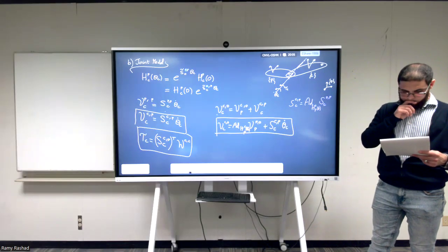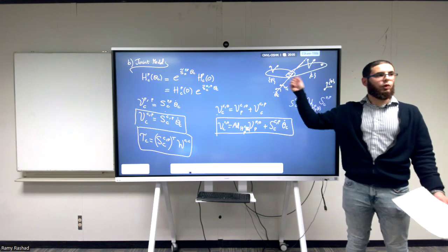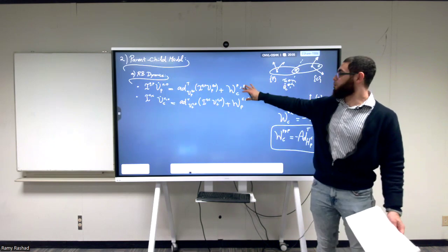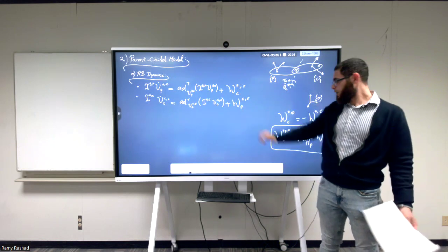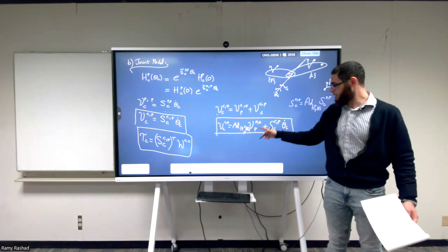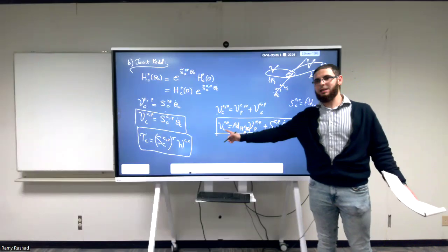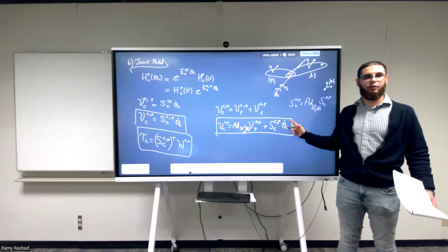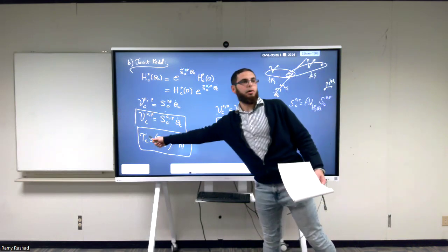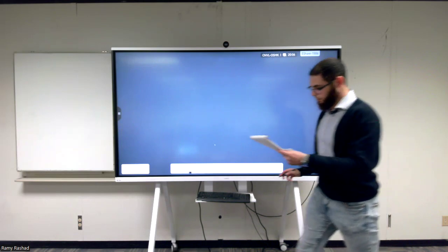Now we're going to be doing something very, very interesting. You see now the joint in the end, what does it do? The joint relates the two wrenches applied between the parent and the child to each other. It relates the relative twist, or the velocity, the twist of the P body with respect to the zero frame, and the C body with respect to the zero frame, and relates it also to the angular velocity. So I have this second relation, and we have a third one that relates the wrench to the torque. Okay, all of these three equations together, I'm going to write them in a very special form as follows.